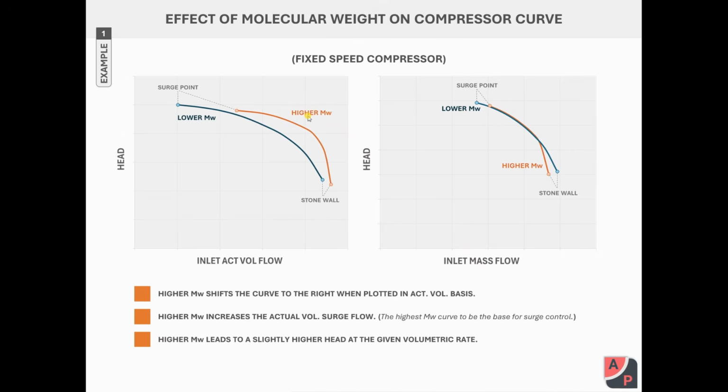And this change in the inherent performance curve of the compressors can typically be analyzed with Buckingham Pi similarity or Buckingham Pi theory. There you can have non-dimensional numbers like flow coefficient, head coefficient, Mach number, and some others like Reynolds number.